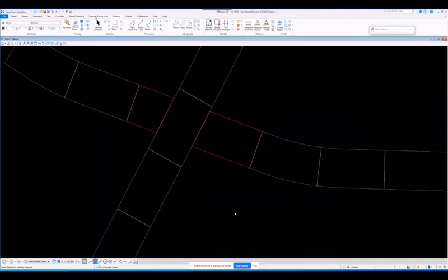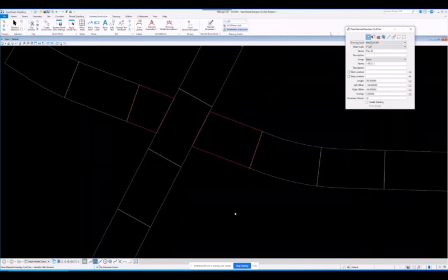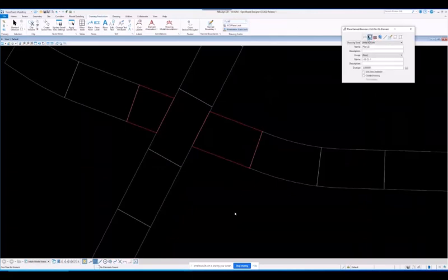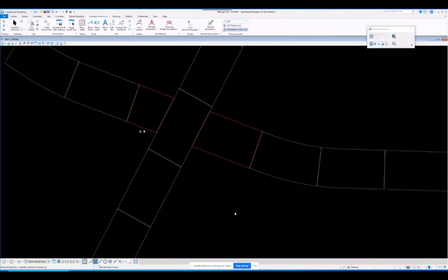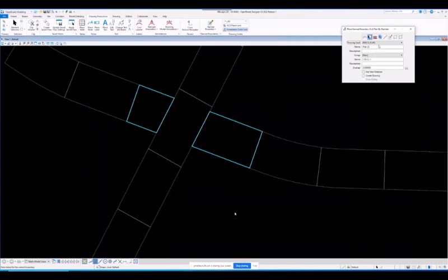I could simply add those to those groups that I created quickly. It's not a lot of work. I'm just going to go in here and say, hey, from a shape, I'm going to make a selection set. 1, 2, it could be 30, 500. I do not care. And basically, I'm going to say, okay, pick that. I'm going to append to the existing group, SR97. And I'm going to give it an appropriate name.